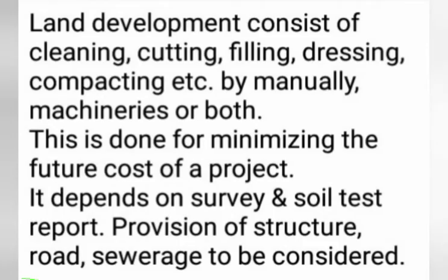Land development generally depends on the survey report and the area of the project. A vast area needs heavy machinery. Based on the contour drawing, cutting and filling of earth is to be done. For procurement of material, making labor hutments, roads are to be made, and thus compacting of land is to be done in this stage. Various soil tests may confirm the requirement.